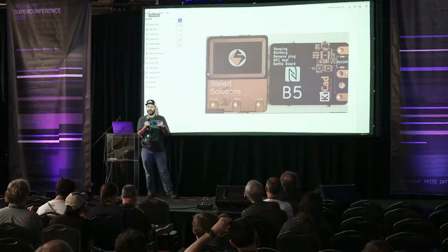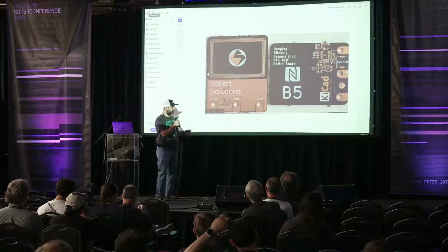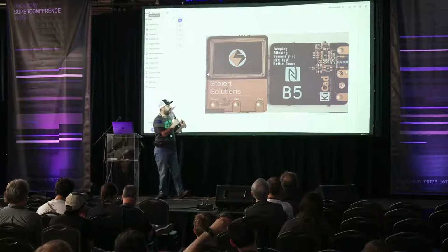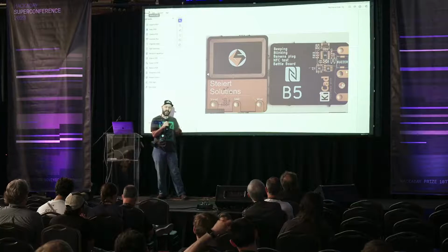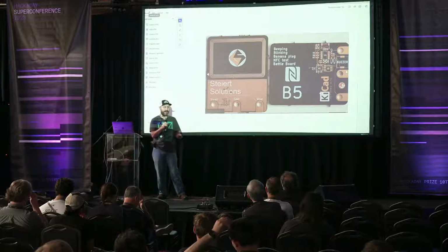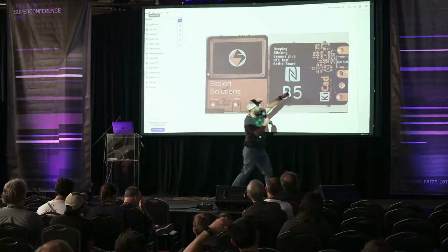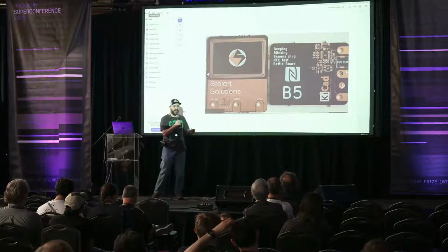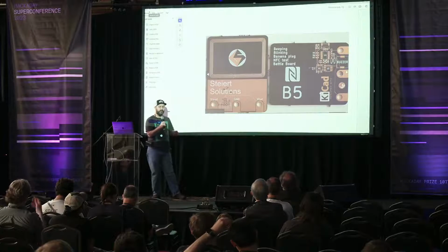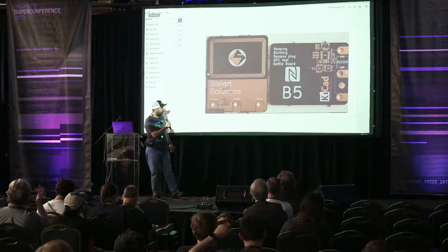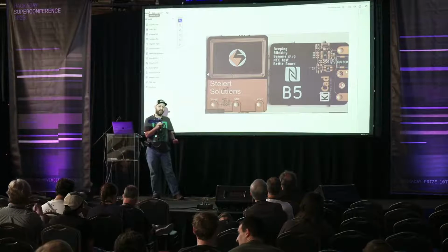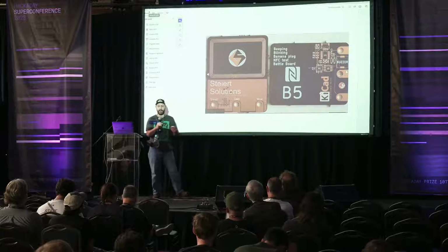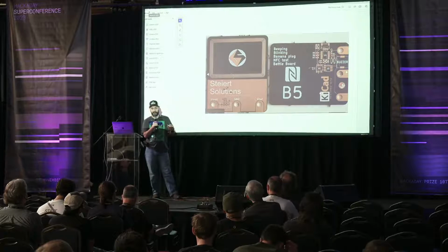Another thing is there's a couple vendors that make these chips. So this one, you see it's called Battleboard, because of course they changed the pinout on their SO8, so they're not compatible. So I put both SO8s on the board, connected to the same antenna so I could measure both. The other thing is the vendors don't do a really great job of talking about how much current you can get out of the chips. So the main purpose of this board was to put both chips down and see which one could give me more current to power the microcontroller.